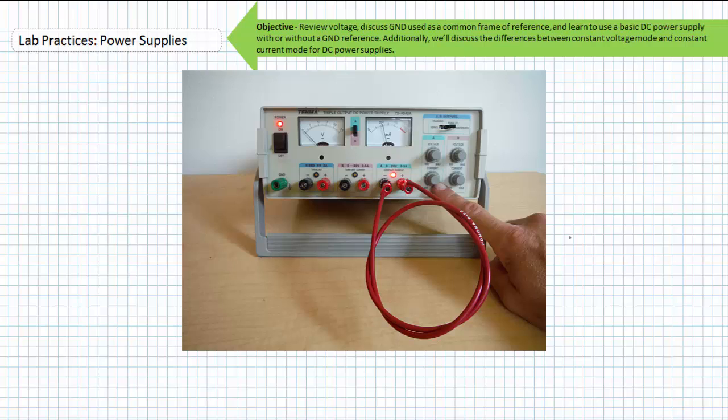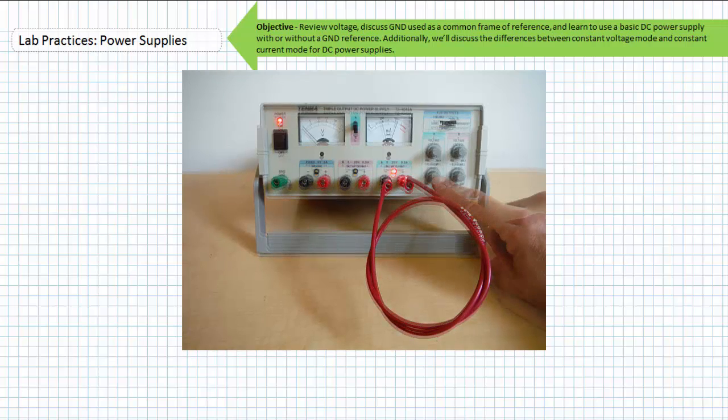Notice the power supply indicates we are in constant current mode or overload conditions with the LED. Additionally, notice the needle meter indicating voltage is not 20.78 volts anymore and has dropped into unreadably small territory, because the voltage necessary to produce a current of 200 milliamperes through such an incredibly low resistance path is so small. If I wanted to, I could adjust the maximum current supplied upwards. I could do so with the current adjustment knob.